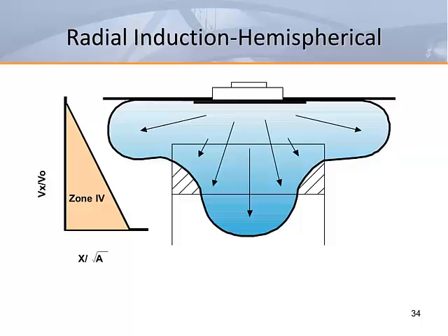While air is distributed outward from the sides of these diffusers, it is usually desirable to discharge the air vertically at the end of the unit, not allowing the air to spread. This high-volume, low-velocity air pattern occurs in Zone 4 of our expansion chart.